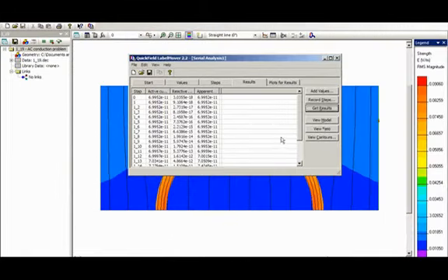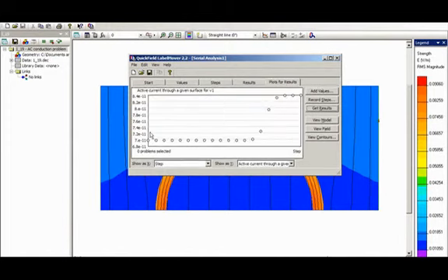Now what I'd like to do is, if you want to take these values and move them over to Excel or MATLAB or MathCAD, you can then extract the different electrical parameters. And we can also plot the results here. This is the active current density, and you can see it was pretty much constant until we're over roughly megahertz, and then we jump up in steps. So the conductivity is actually going to be jumping up in steps here. This is in the beta range.